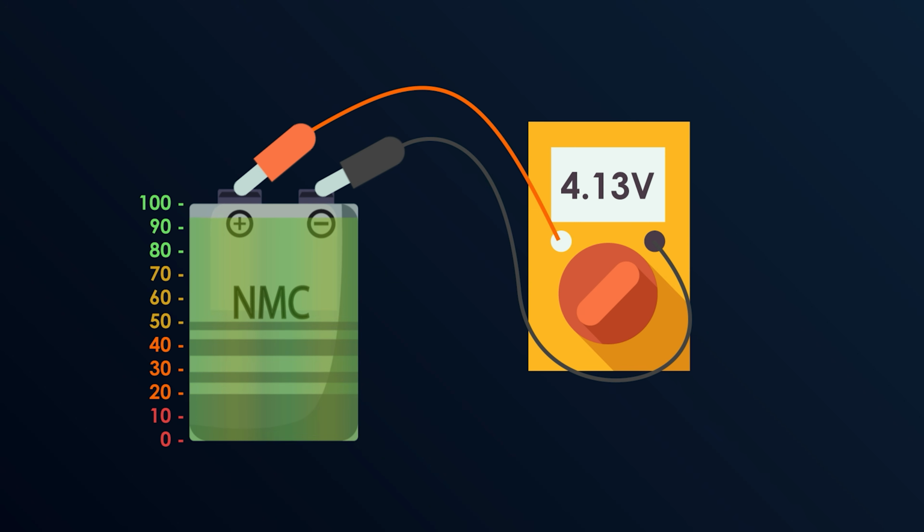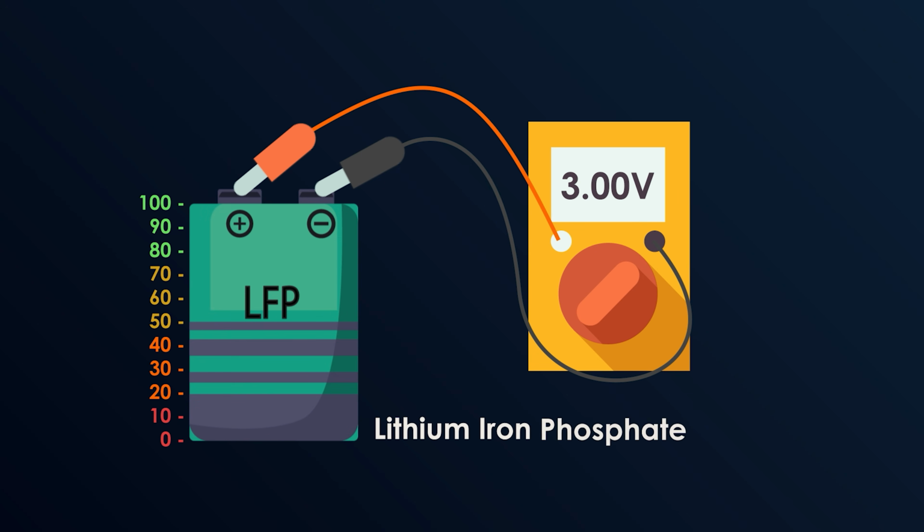With a normal NMC battery, which we have in our phones, the voltage is a nice cooperative sloping slide. Every 1% of charge drop comes with a clear measurable voltage drop. It is easy for us to track. If you still think those standard batteries are tricky, we need to look at lithium iron phosphate or LFP batteries. These batteries are the worst for SOC estimation.